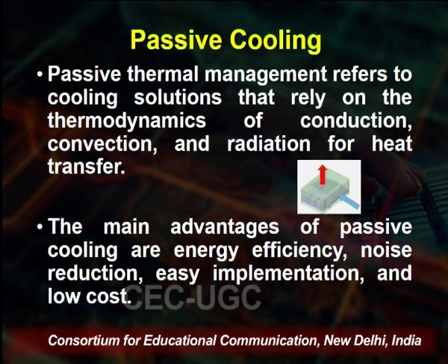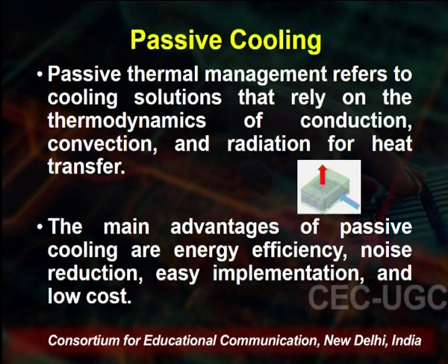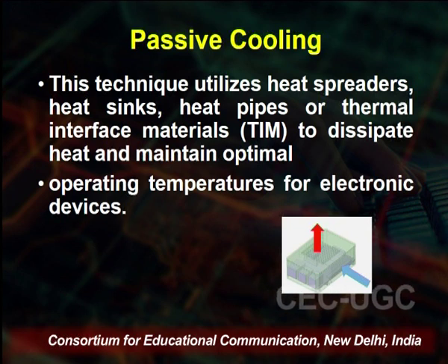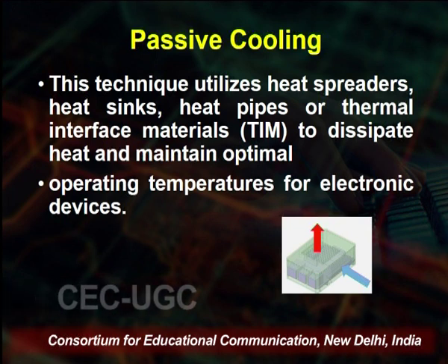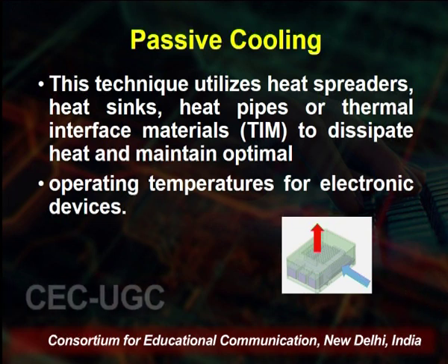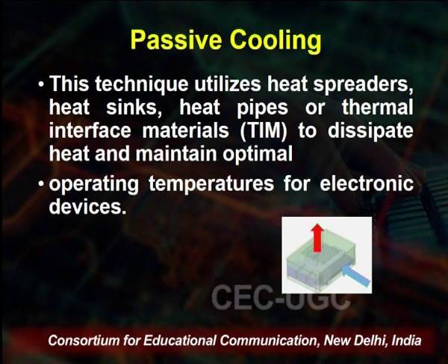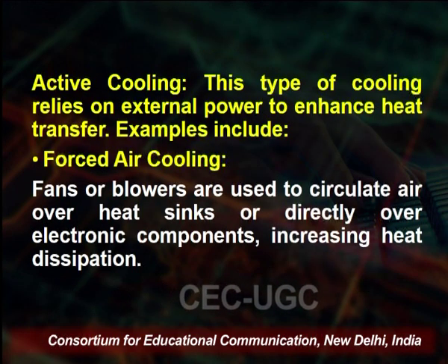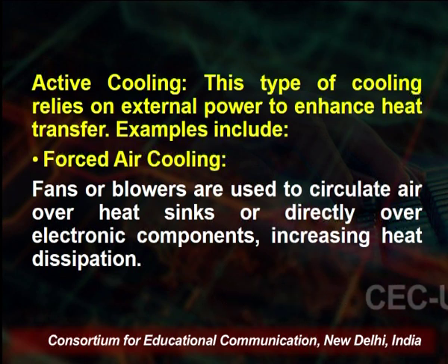The main advantages of passive cooling are energy efficiency, noise reduction, easy implementation, and low cost. This technique utilizes heat spreaders, heat sinks, heat pipes, and the thermal interface material, that is, TIM, to dissipate the heat and maintain the optimal operating temperature for electronic devices.